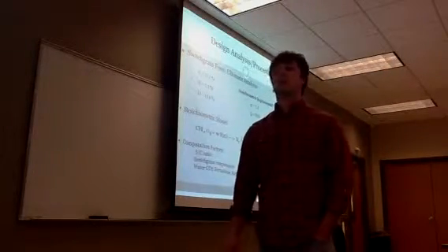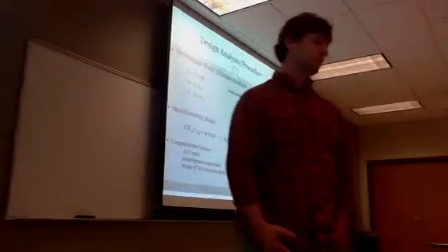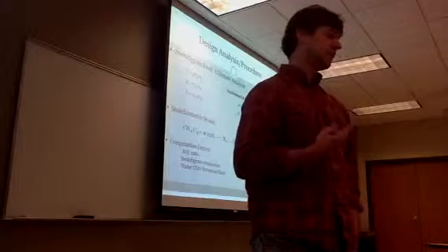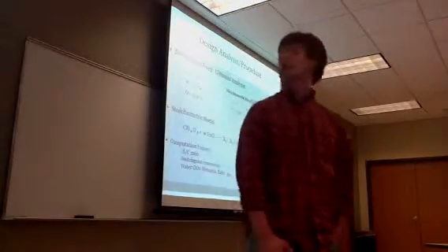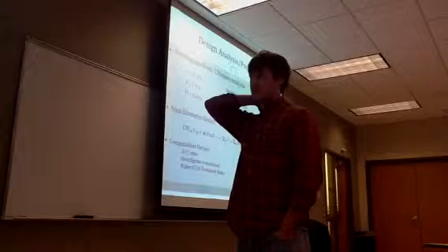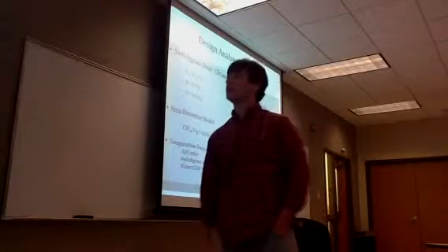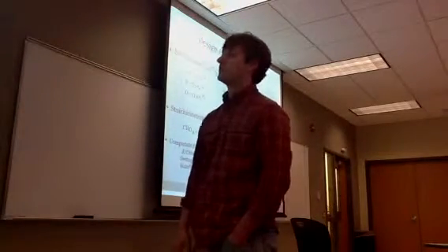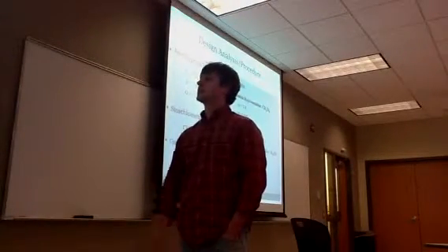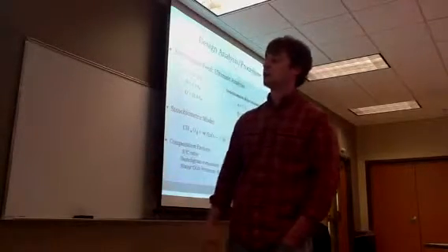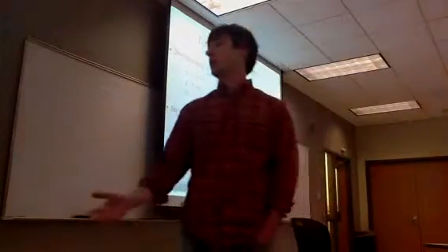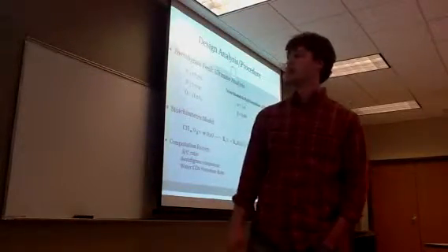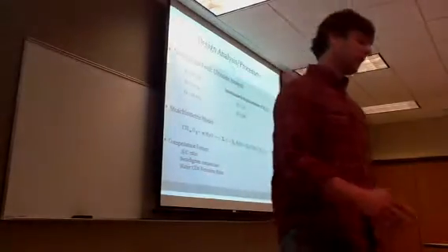CHO, biomass. Switchgrass is composed of three main constituents: cellulose, hemicellulose, and lignin. That breaks down into a simple formula like this, and a stoichiometric model is formed from this equation, with x being the molar amounts. Using some computation factors such as our steam to carbon ratio, our switchgrass composition, and our water to CO2 ratio, we have 5 equations and 5 unknowns, and using stoichiometric relations we come up with a working reaction.